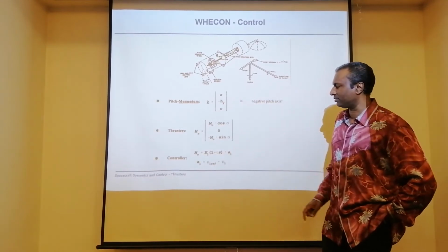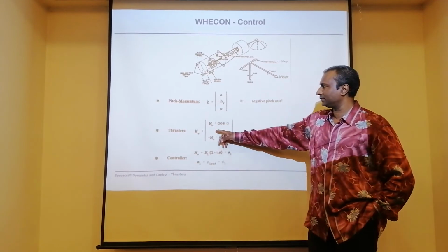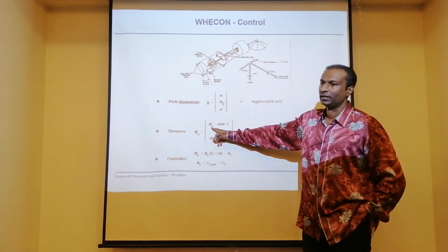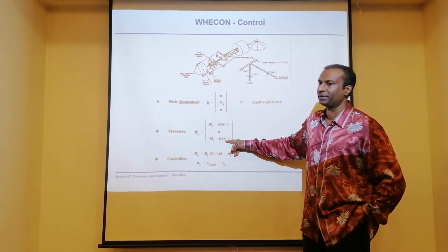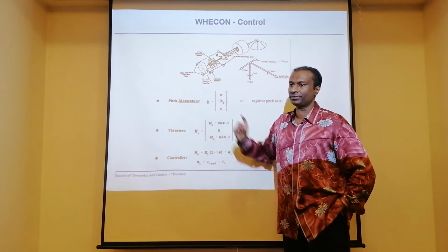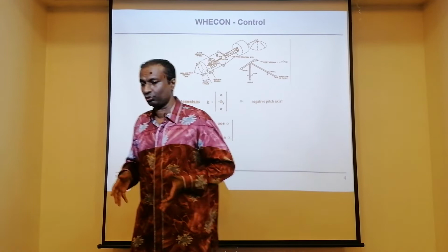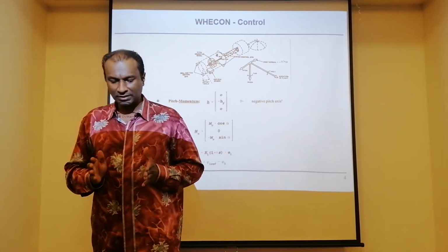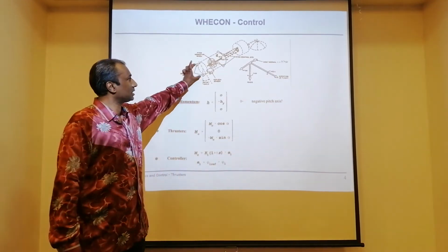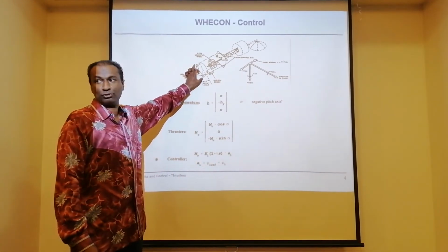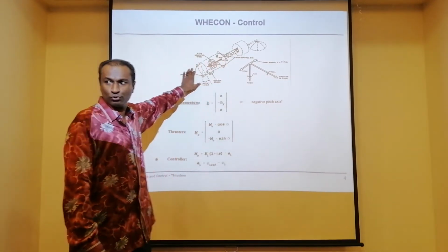The only thing I've introduced today is this thruster torque. Basically, I can say that the thruster torque would be the cosine angle or sine angle of the particular configuration. Now, why this design? Remember, the thrusters can also be used for translational motion. So there is a design consideration that these thrusters can be used not only for attitude but also for translational motion.